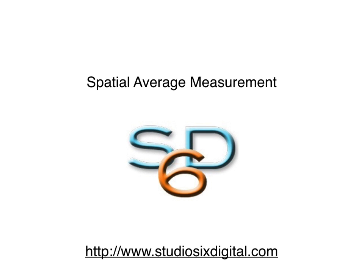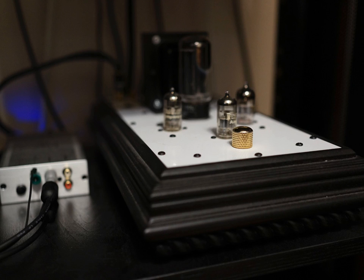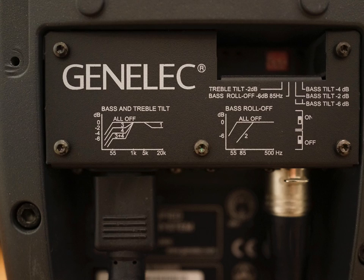A useful technique for characterizing how a loudspeaker sounds in a room is to measure a spatial average around the sweet spot. The technique here is to measure IRs around the listening location and take an average. This helps to smooth out modal behavior and gives you a reasonable impression of the frequency response that you are actually hearing from your loudspeaker. This technique is useful for setting tone controls on a preamp or receiver, or general equalization of your system. This is also a useful technique for setting the EQ settings present on many active studio monitors or DSP equalizers.